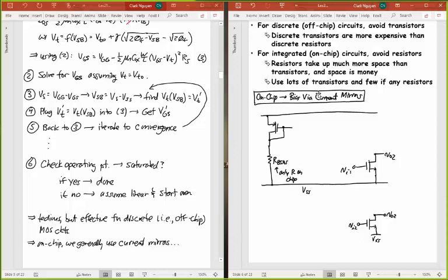Okay, but the important thing is that if this is my transistor, which I'll call M1, so for MOS transistors, I'll call it M1. And if I size M1 to be W over L1, then what's going to happen is I'm going to drop a voltage across this, and that voltage dropped across this is going to be the VGS of device 1.